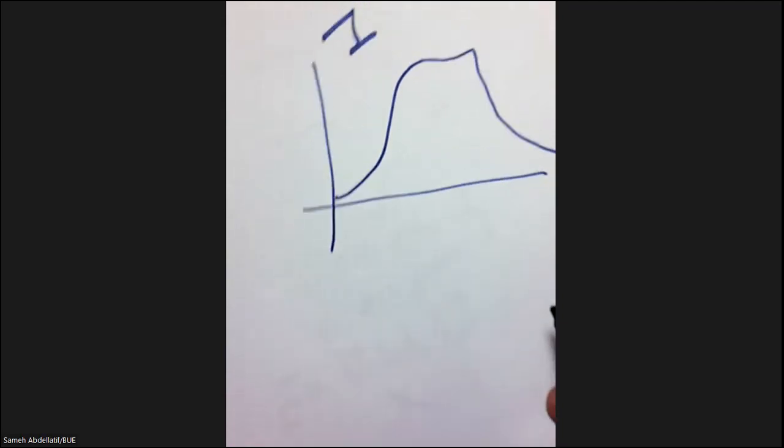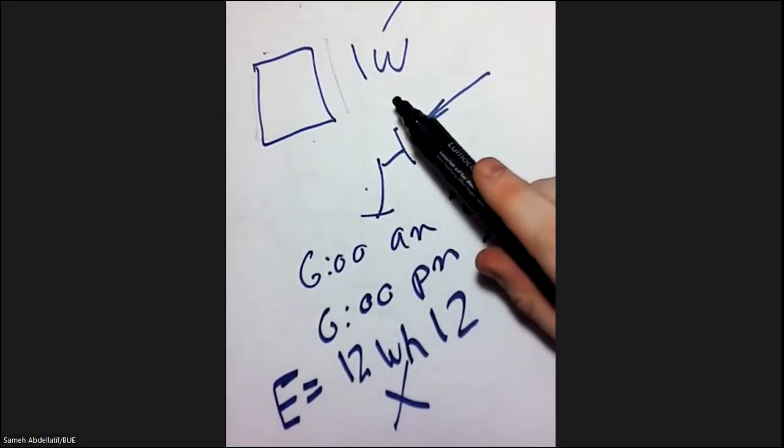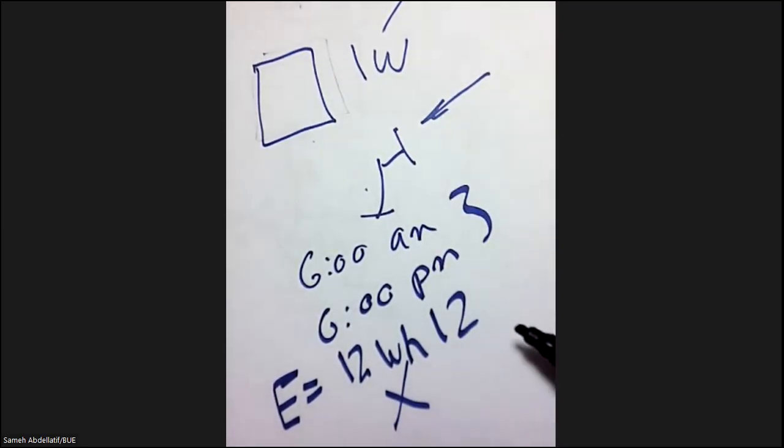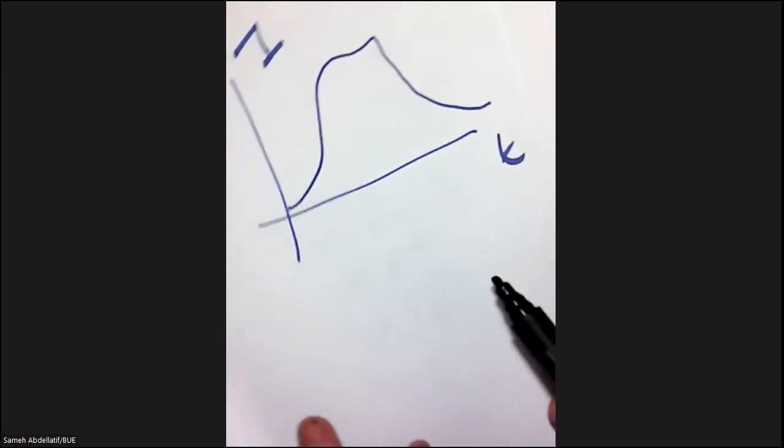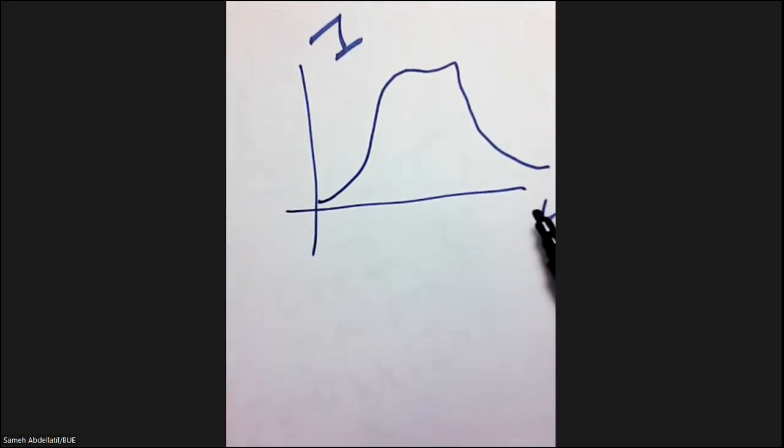So when you multiply, my dear students, 12 by 1, you assume that the whole 12 hours are of 1 sun condition of 1000 watt per meter square, which is typically wrong, because not all the time will the sun be in the 1 sun condition. For example, in the early morning at sunrise or in the late afternoon at sunset, the intensity of the sun will definitely be very weak.